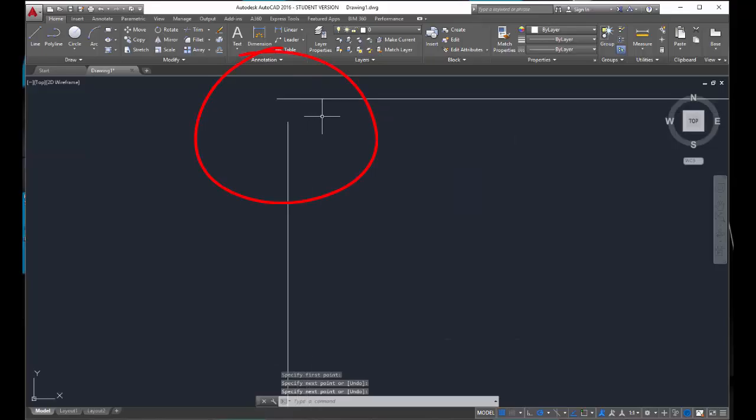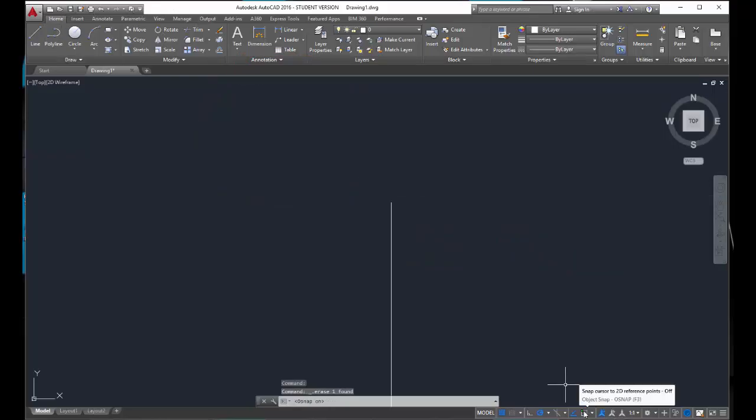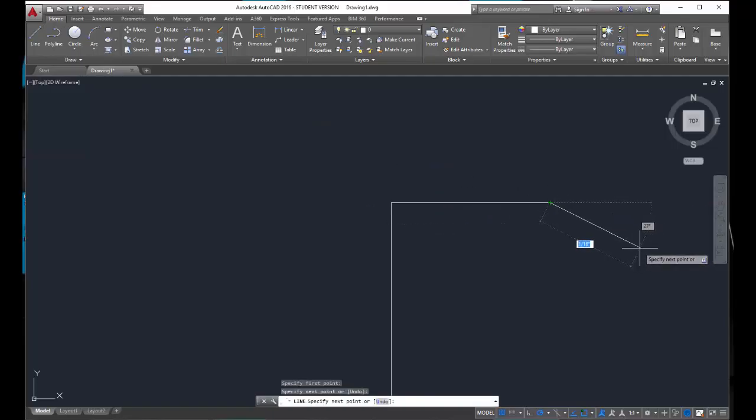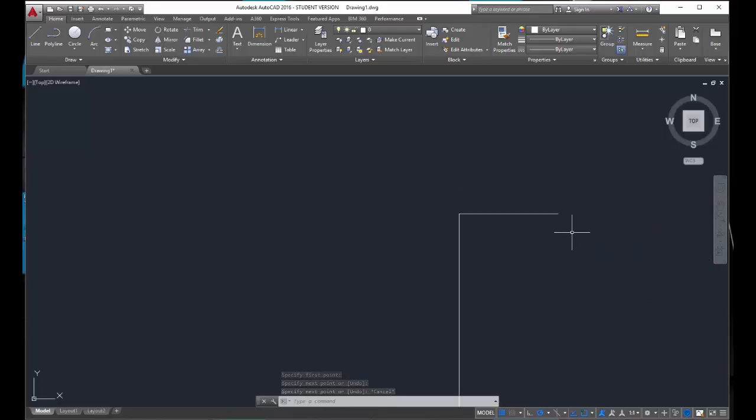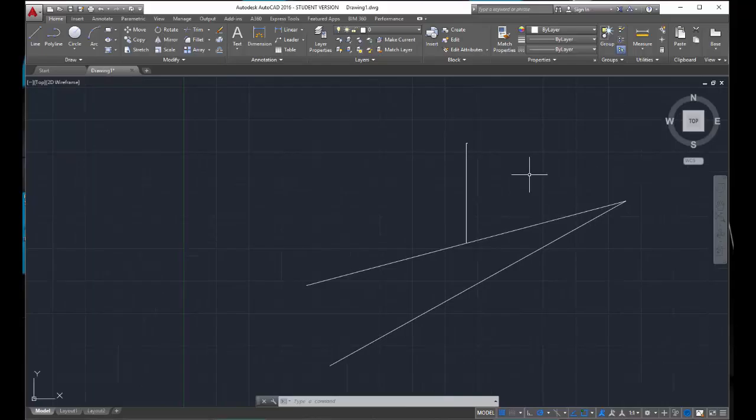So click, draw a line, enter. Wow, yeah, see, this is what we want to avoid at all costs. This can cause your measurements to be off. It can cause a lot of things to be off. So when we're drawing, I'm going to delete this line for right now. I'm going to turn Object Snaps back on. And here we go. I know that that line is perfectly placed at the end of the other line, and nothing is going to be off. I'm going to be drawing correctly. Just so that you can see how far in we were zoomed, pretty far in.